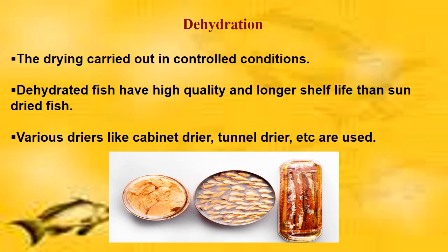So when the drying is done under vacuum, the evaporation happens at a low temperature. In that case, the denaturation of protein is less and such a dried product will have better rehydration ability, so the quality will be much better.